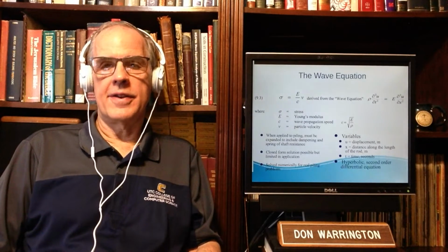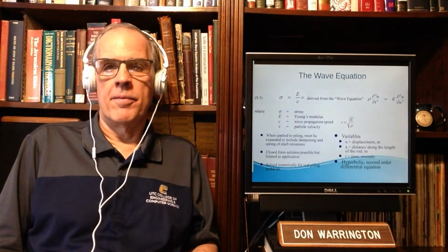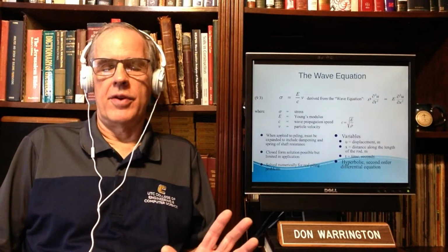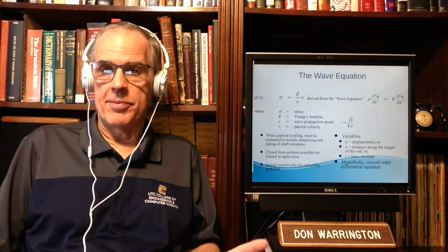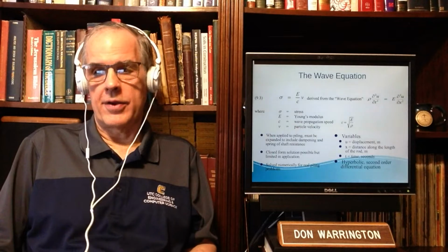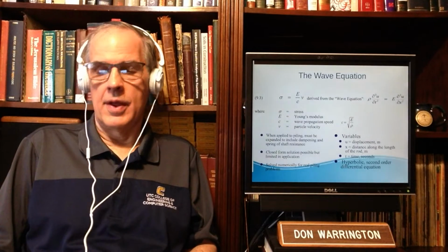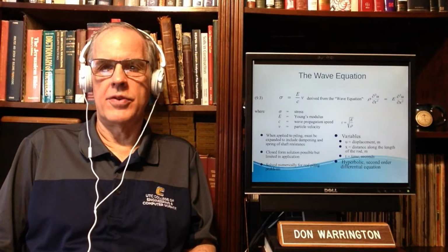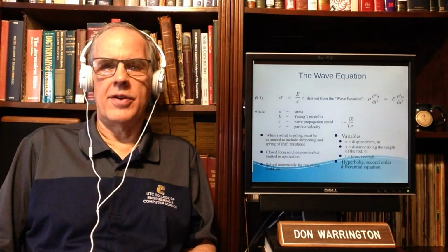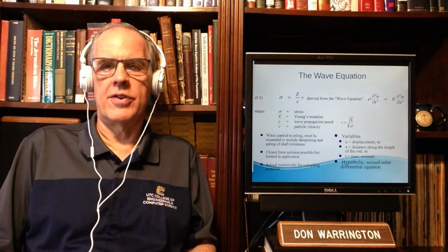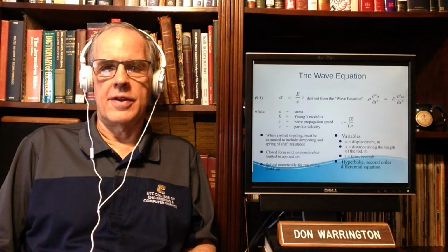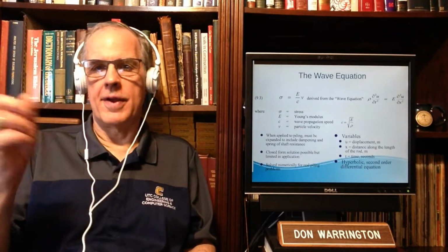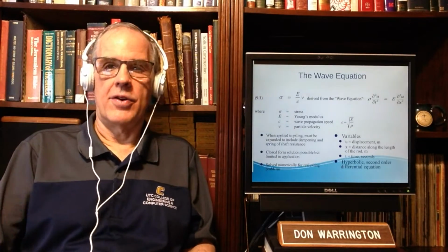Both Isaacs and Glanville used the undamped or simple formula for their calculations. And they used what's called D'Alembert's method to do that, which is as accurate for that. If you don't have any shaft friction, it works. What tripped up both of them was that the math of waves going up and down the pile gets complicated in a hurry.